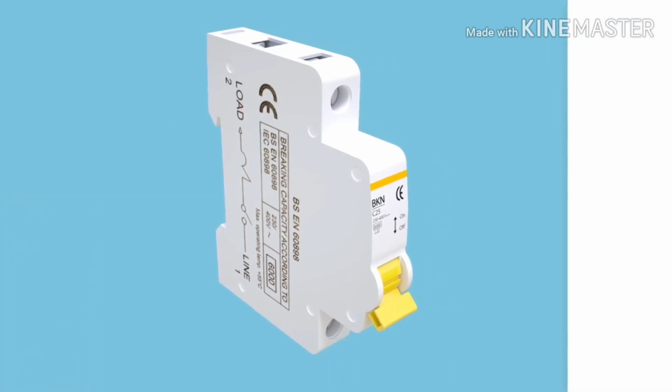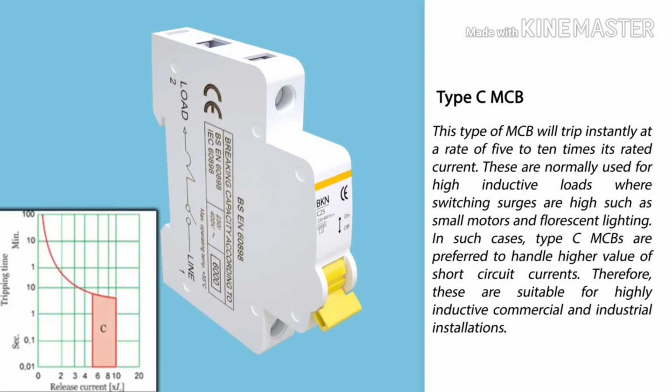Type C of miniature circuit breaker. This type will trip instantly at 5 to 10 times its rated current. These are normally used for high inductive loads, where switching surges are high, such as small motors and fluorescent lighting. In such cases, type C are preferred to handle higher values of short-circuit currents. Therefore, these are suitable for highly inductive commercial and industrial installations.